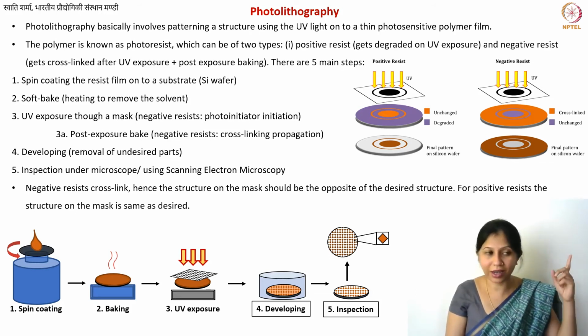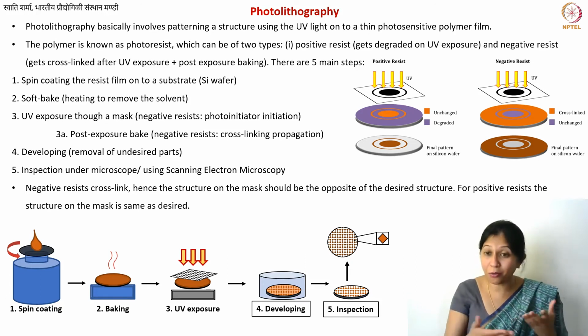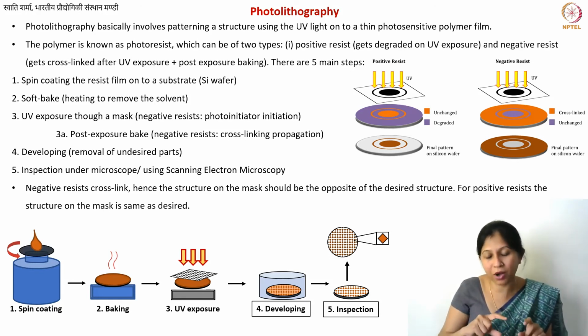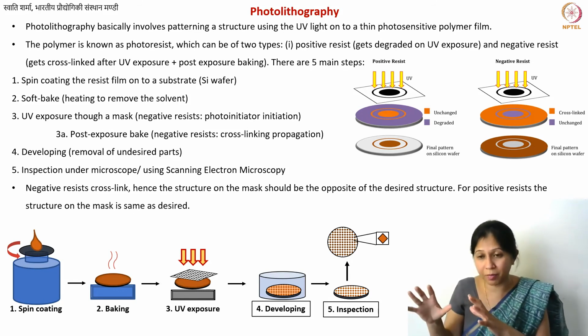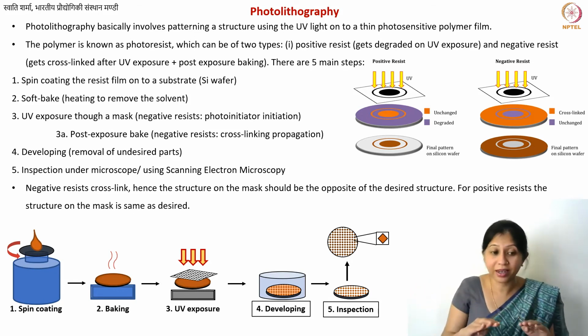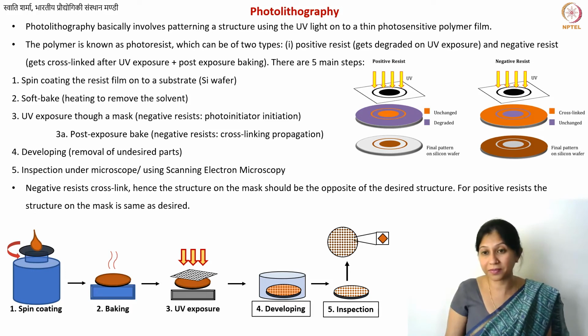Now you can also think again of the models that we had discussed. There is a coexistence of curved carbon structures along with these larger, turbostratically arranged carbon sheets. And in some cases, if you keep on heating it, let's say to 3000, these turbostratic sheets, not the curved carbon parts, have a possibility to convert into graphite or to become more graphitic, which would give you slightly higher electrical conductivity, maybe also better mechanical properties.